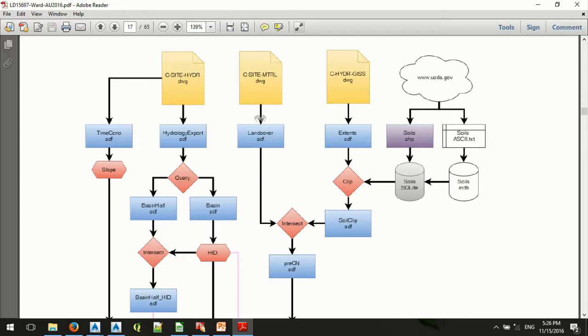You've got a material file, and you've got a separate GIS workspace. Everyone is welcome to set it up their own way, but I've found that I keep the GIS stuff separate from the Civil 3D stuff, because Map 3D is so much less stable than Civil 3D. When it crashes and you get a fatal error and can't recover the drawing, it won't contaminate the rest of your data.